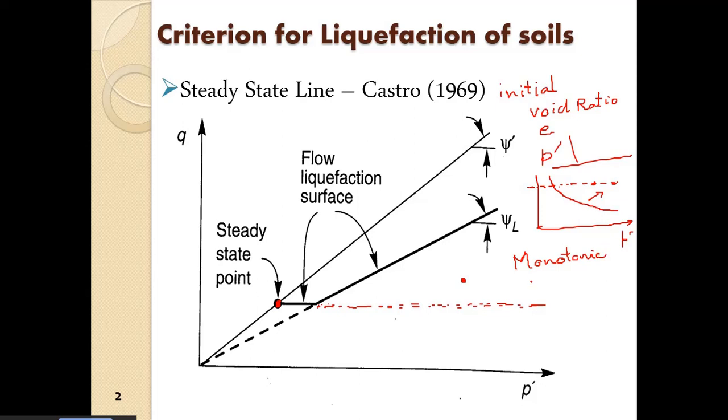and the other is if we apply a dynamic, vibratory or oscillating load, so the shear stresses change their direction. Once it is in this way, and the other time it is in this way. So the two stress paths will plot in different ways. If we apply a monotonic load, definitely a huge amount of deviatoric stress has to be applied, and it will move in this manner,